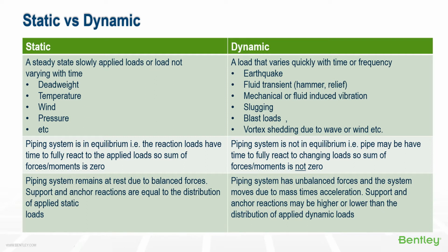Dynamic loading tends to increase the response of the structure beyond the response obtained if the same load is applied statically. A static load produces a system in equilibrium with reactions at supports equal to the sum of the applied loads. AutoPIPE offers two types of solutions for static loading. The difference between these two solutions is in the treatment of the supports and the soil and how they handle the nonlinear effects. Most supports in real life have gaps and might offer frictional resistance.